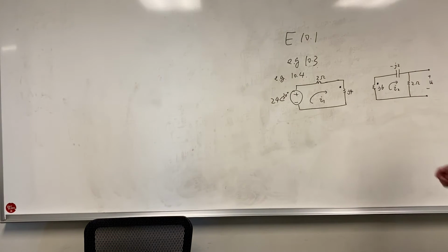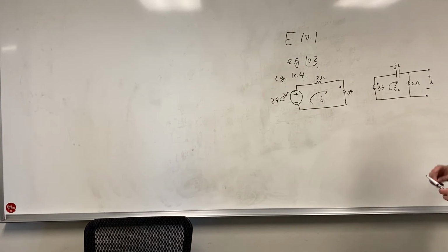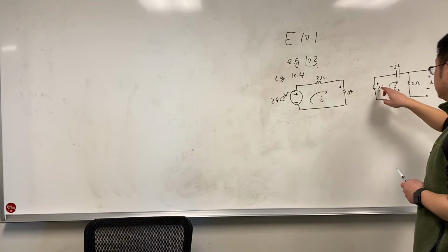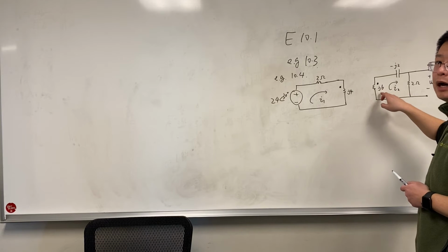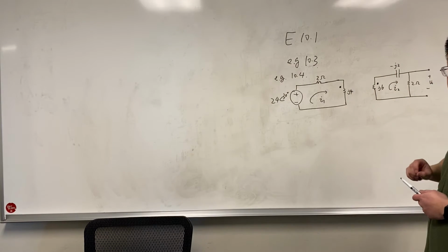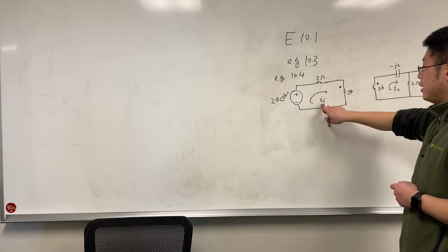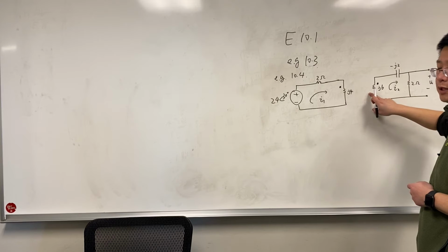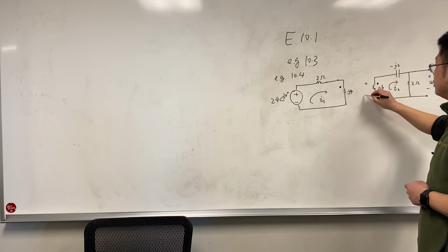So in this one, you need to calculate the output voltage VO. So we have two loops, the loop 1 and the loop 2. And the current I1 is entering the dotted terminal, and in loop 2, the I2 is entering the undotted terminal. So first we write the induced voltage. For this I1 entering the dotted terminal, it will generate a voltage at the secondary winding, which is also positive at the dotted terminal.